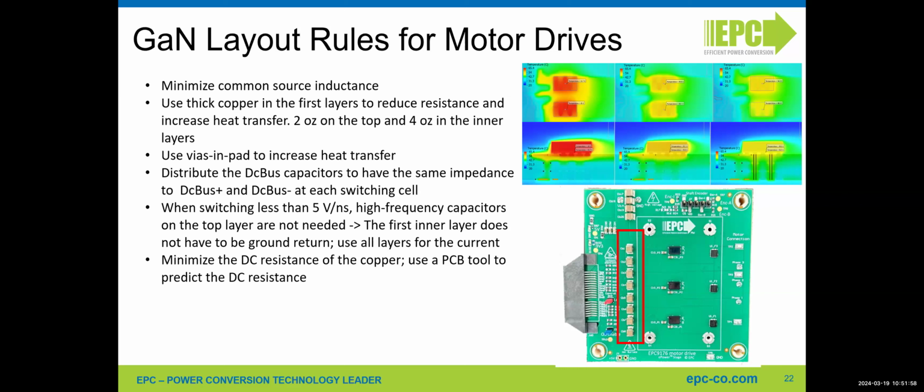It's a thermal problem in general. When you start working with gallium nitride in motor drive, first you think about the thermal design, the thermal circuit you have available and the thermal budget you have, then you understand how much you can dissipate, and then you understand what you can do. Here we wanted just to get the highest current we could.